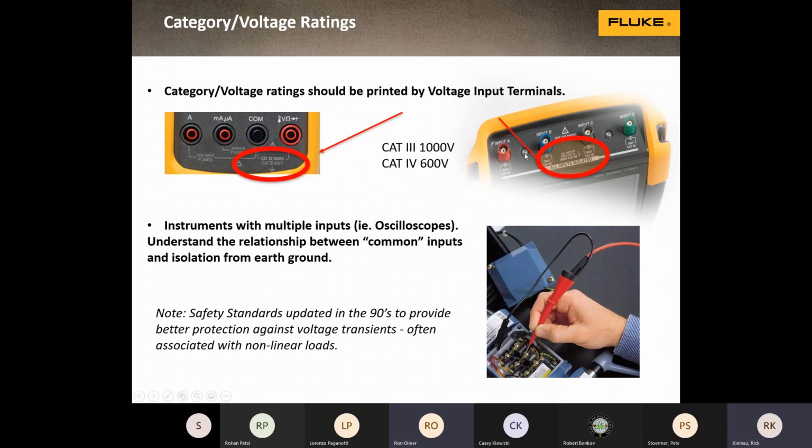So you could measure voltage phase to phase on one input, no problem. And on the other input, put a clamp if you want to measure volts and amps at the same time. But I wouldn't advise making two voltage measurements if one of these connectors is connected phase to phase. Yes, I understand. Okay, great.